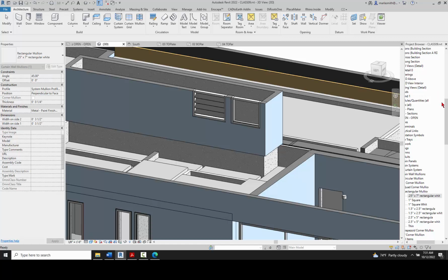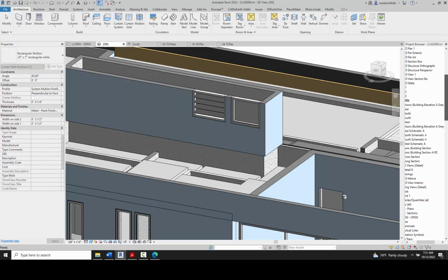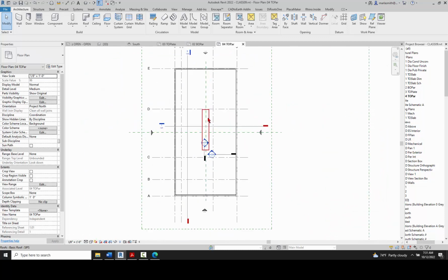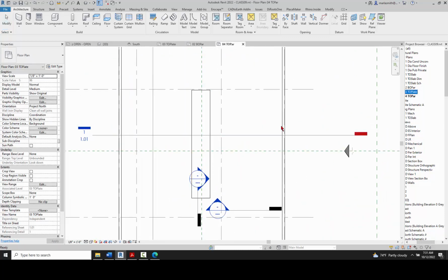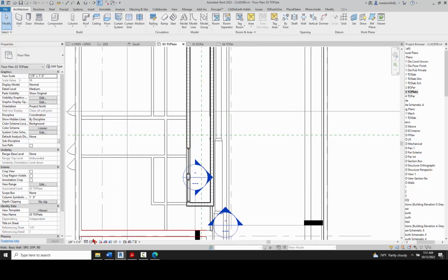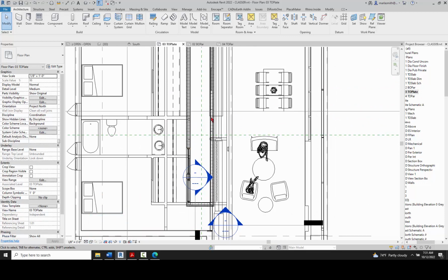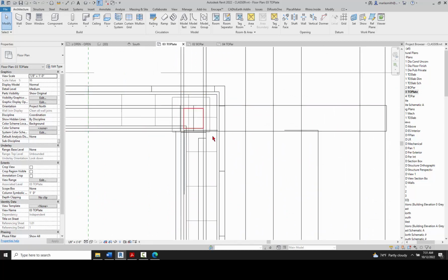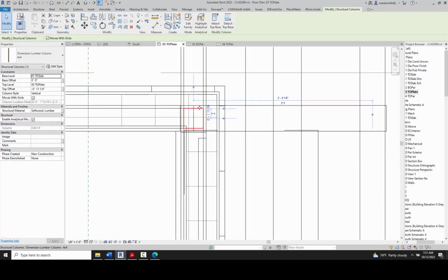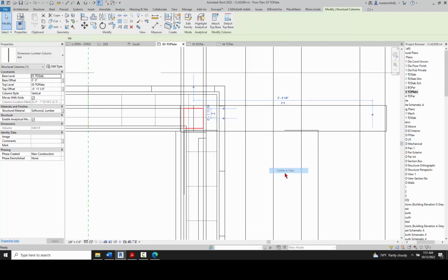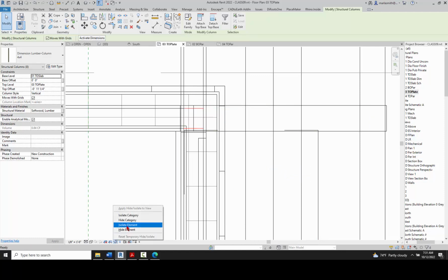You can look at the dimensions from the floor plan. To put the posts in is pretty simple, so you can go back to your top of parapet. If I zoom out, or actually sorry, top of plate, and if I zoom out and I go to wireframe here, right, I should be able to get in there and kind of see where those other, like I can pick that, and if I come in here and select all instances visible in view, then I can isolate those, right?